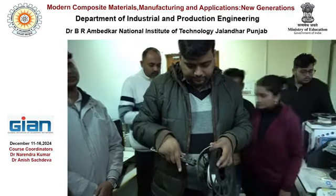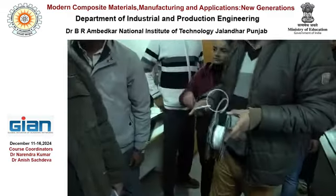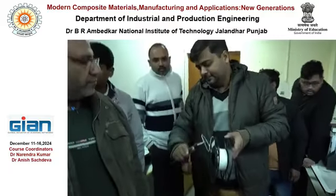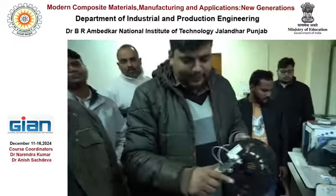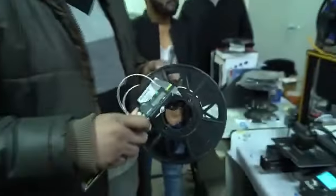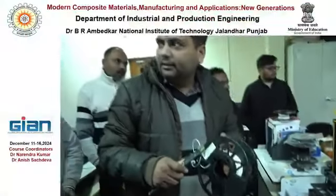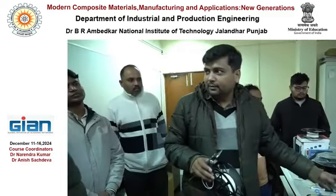See the diameter. Now it is exactly 1.75. So if you are planning to make any composite material, suppose you want to blend PLA with any other filler material, you have to ensure the diameter. Otherwise, what will happen? The hardware will not support your filament, right?